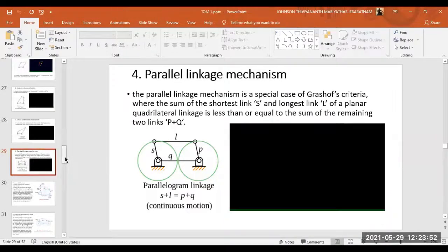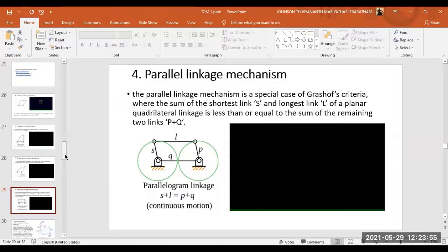So based on changing these different linkages, right, and changing the lengths and changing the ground links or fixed links, we can make different types of motion. All of them are four bar mechanisms, right? Every mechanism has only four links, but one is giving you a double crank, one is giving you a double rocker, the other one is giving you one crank and one rocker, right?